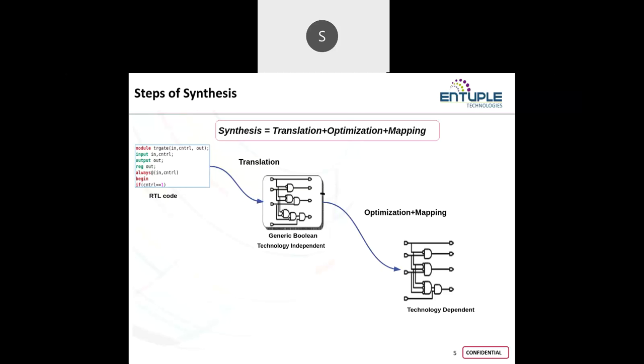And you can also see the gate level netlist. Usually the netlist by default will not be generated, so again you need to make use of a write command. Write underscore HDL is a command you will use for writing out the gate level netlist file, and similarly for generating the SDC file, along with the report files. In the GUI mode, the graphical user interface mode, you can directly see the reports.